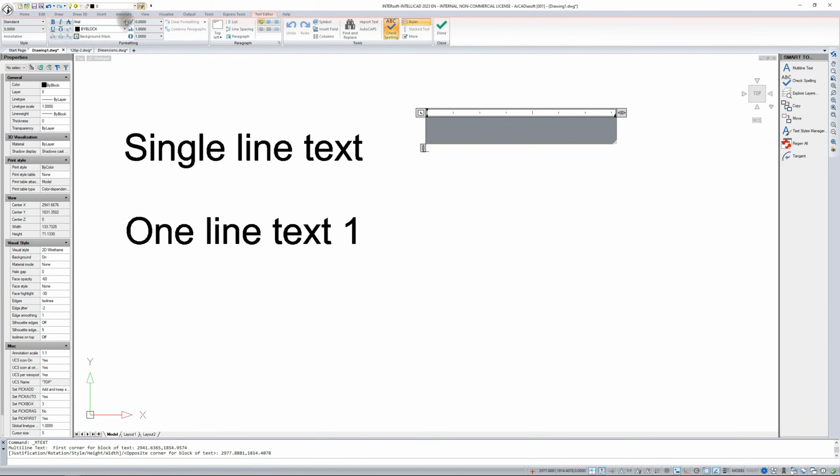Bold or italic will not apply to all fonts because remember that the program uses TrueType fonts, such as Arial, and they will undoubtedly be subject to these modifications. However, fonts such as SHX or with technical fonts, bold may not work because they are drawn with a line. More or less in the middle part, you have options to determine what happens to the text, whether it should be left aligned or right aligned, whether it should be justified or centered.